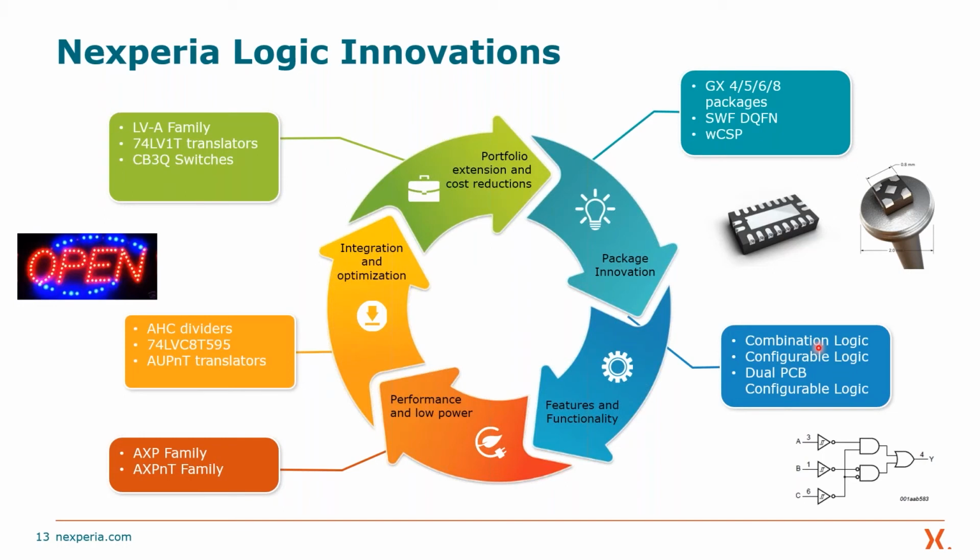For example, if you need one AND gate and one OR gate on your circuit, that meant 2 packages. However, why can't we combine them? So we have a whole family of parts where the single package has one AND gate and one OR gate on it, or 2 buffers and 1 inverter, or an inverter and an OR gate. The wide variety of combinations to help you reduce the size of your design by combining these parts together into smaller packages. So it's kind of a packaging logic trick, so to say, that defines new part numbers.